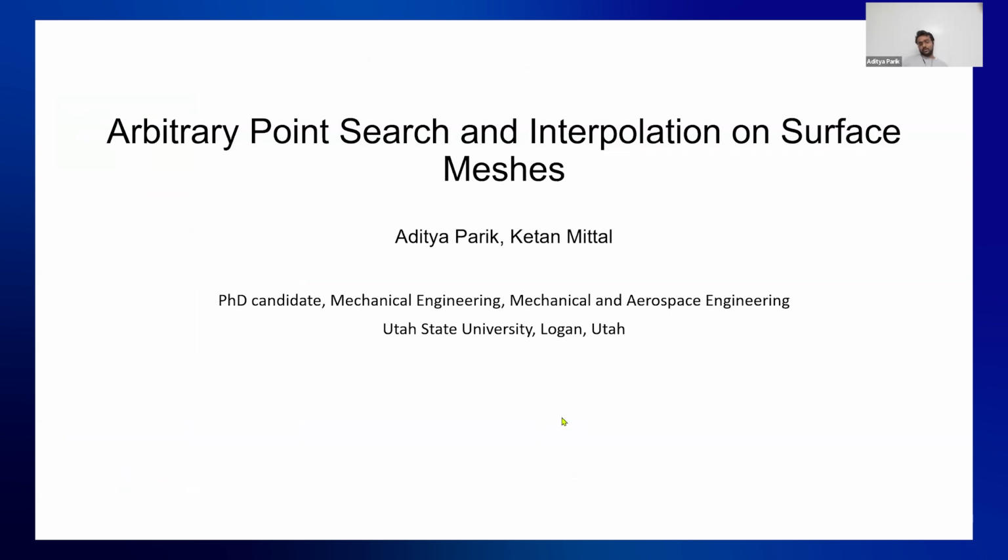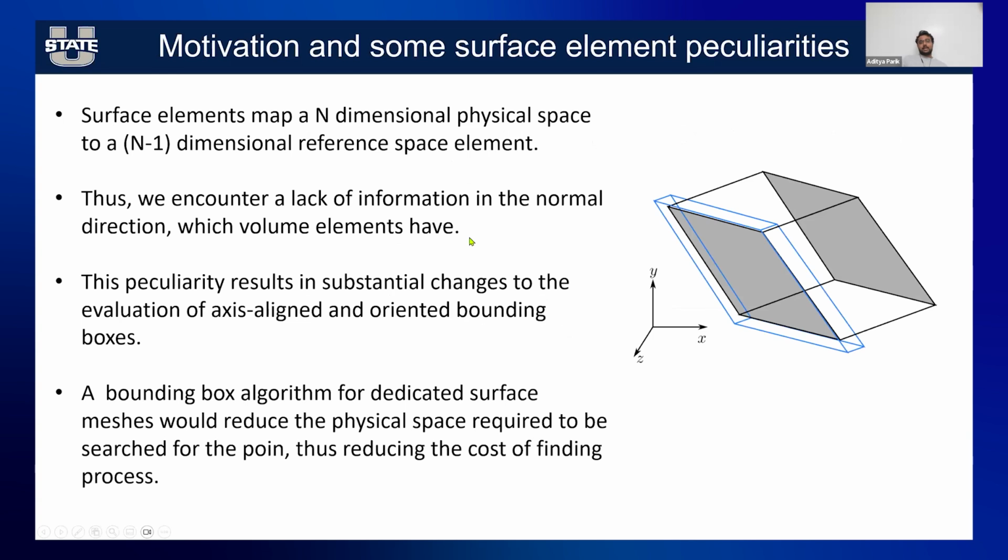Today I will be presenting the work I did with Ketan during the summer in attempting to port the routines that exist for find points for volume elements to surface elements. Of course, this is given the understanding that surface elements go from a three-dimensional physical space to a two-dimensional reference space, and that doesn't provide us with information in the normal direction that we would need to describe the bounding boxes in the normal direction of the element. And so, given that restriction,